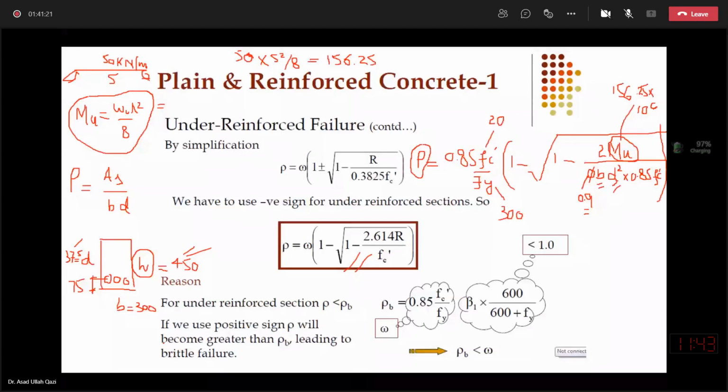So we start from 228 millimeter, normally 9 inch, because in some cases we want to conceal the beam within the wall. We want no offset above the wall. But if the beam is wider than the wall, there will be offset. If I want to conceal it just above the 9-inch thick wall, then I may prefer B equal to 228 millimeter, 9 inch.